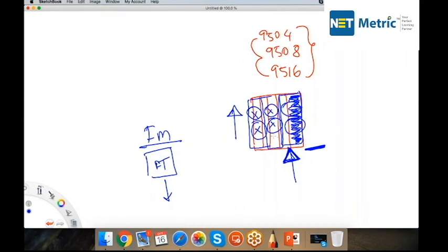First thing is, removing 2 fan trays at the same point of time is not supported. If you do that, your device is going to reload every 3 minutes. And eventually, once the heat has reached its maximum temperature, all the components will shut down. Removing two fan trays at a time from one device is not supported.